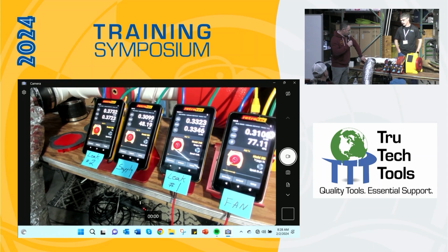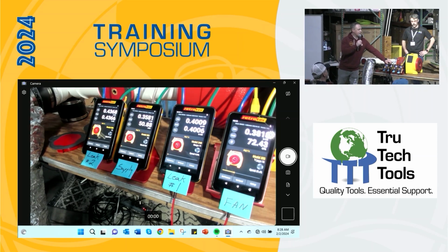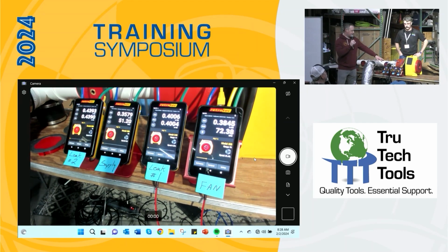And in the middle here, we have a supply duct. I'm just going to cap this one back off to bring that static pressure back up. So we can see that the total flow right here on the fan is about 72 CFM that we're moving through. Let's see if I can get that glare off for you guys. There we go. And about 50 of that is coming through the supply duct. Static pressure is kind of remaining the same. It drops a little bit right when it gets here.